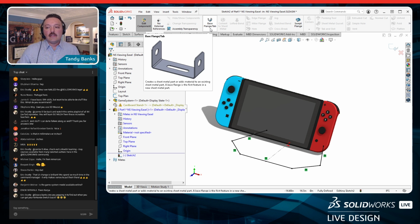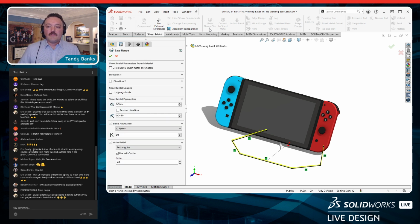As you can see in the little flyout description and the picture there, that's basically what I want to do. I want to take my sketch entities and extrude them up in order to create my first sheet metal feature. But what we do when creating that first base flange is we're also setting up all the parameters related to our sheet metal properties. So there's a little bit more going on in this very first dialog box, and I'm going to spend a little bit of time unpacking some of that.